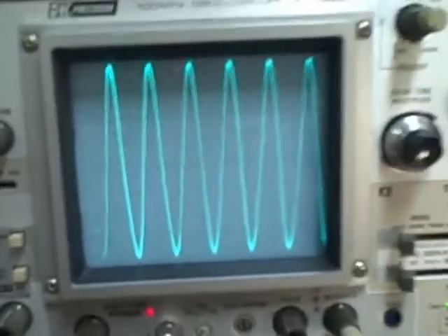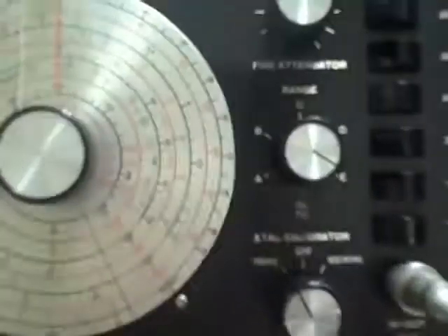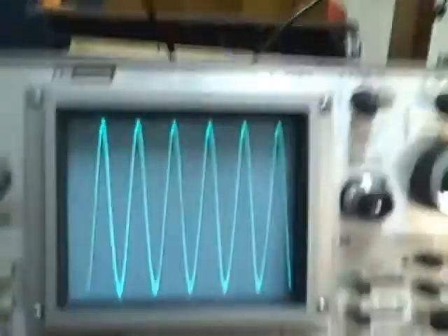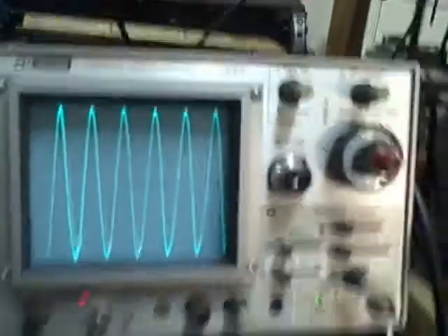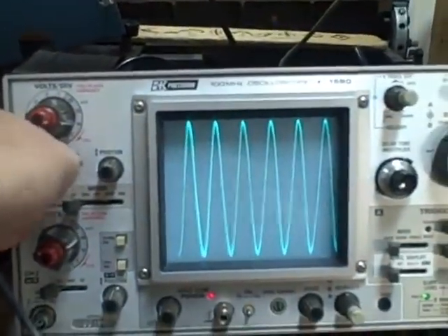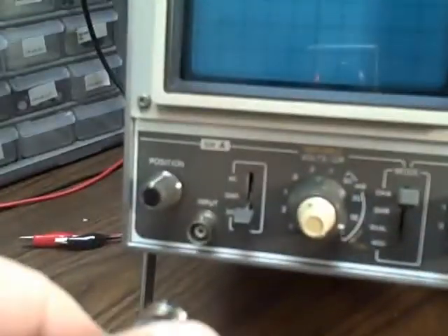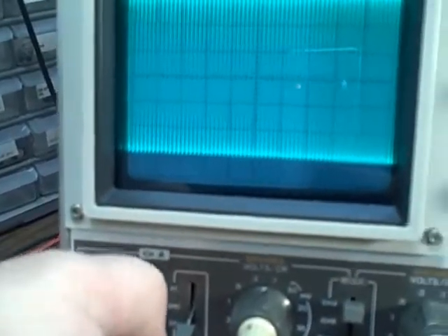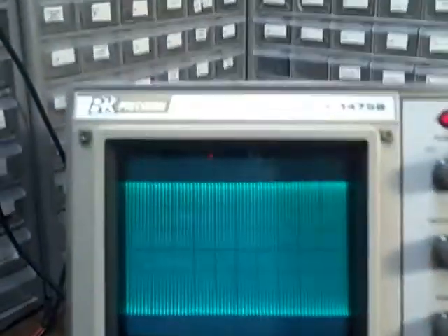Let me point out that I am on band E of this B&K E200D, and we are at the 30 megacycle range right now in band E. Just proving my point. What we're going to do now is move the test probe from the reference scope, and insert it on the B&K, 30 megahertz B&K.